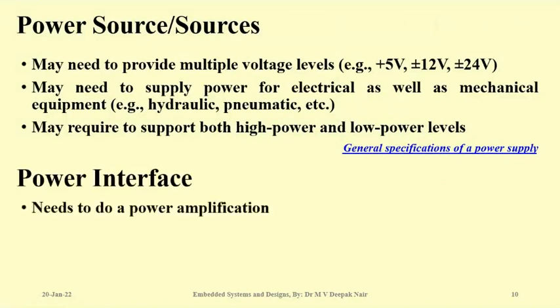Of course you will need a power interface when you need power amplification. There is a difference between power supply and power amplify. Amplify means increasing the power. In the last class I showed you connecting a transistor to increase the power. From the source you were getting a very small power, but at the end you were driving a motor with a larger power. That kind of thing is power amplification, and for that we use transistors.